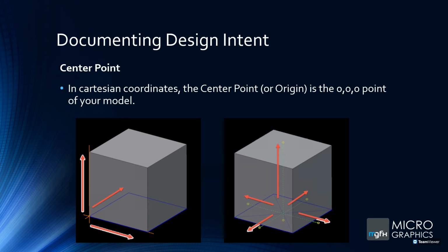One thing you want to do is, when you're creating parts and you're going to be resizing them, getting longer or shorter or higher, you want it to move in a predictable way. For that, use your 0, 0, 0 point, your origin, and either constrain it to the bottom left-hand corner or the middle. In the first picture there, you can see that it moves predictably to the right, down to the bottom right, and up. Whereas if I constrain the center of that rectangle to the origin, it will move left, right, up, down, and up to the Z-axis as well.